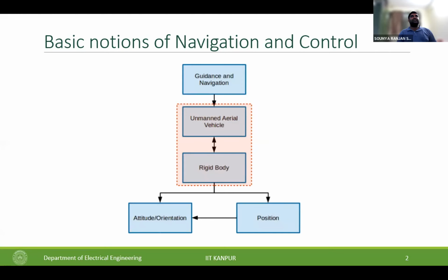So what you can essentially generate as a command is the position and the heading of the vehicle, of which the XY motion gets converted to roll and pitch, as I said, and then the roll and pitch are actually realized by the control laws of this vehicle, which results in this X and Y motion.